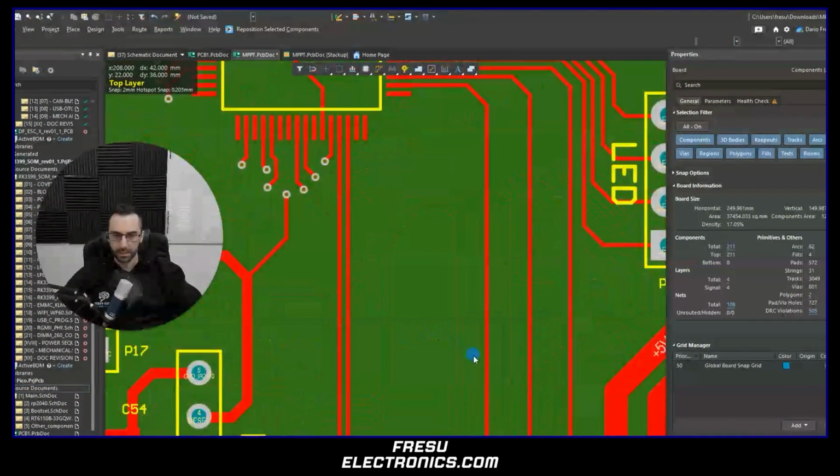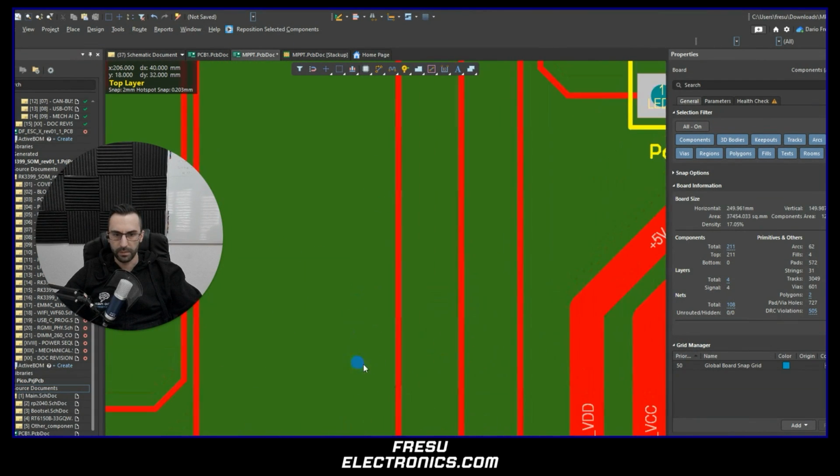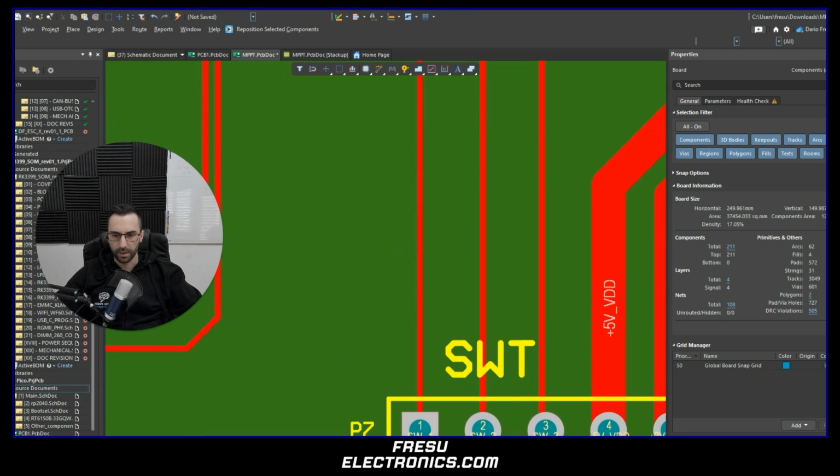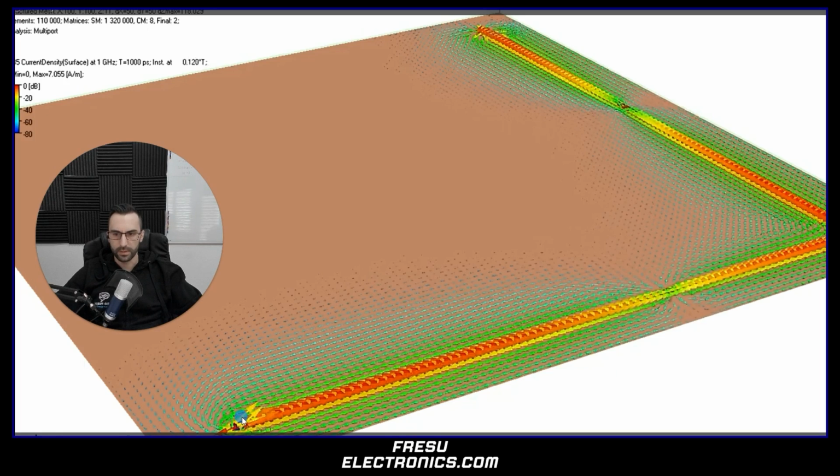You can see that in this PCB, for example, we have the top layer with the signals on the top, and then we have the plane, which is a full plane without cuts, without splits. So this is a full return reference plane. We're going to see how the signal behaves when it's running at different frequencies. We will have different signals here: one is going to be 1 gigahertz and the other one is going to be 10 kilohertz. And we are going to see how the return currents behave in these circumstances.